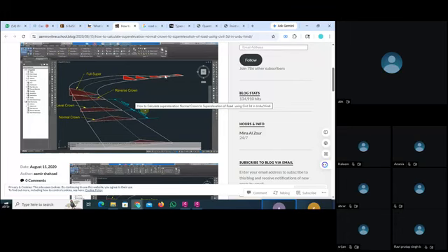When you read the super elevation theory, you can go through all these crown parts. This is the normal crown you can see in this shape. When our shape changes from this to this, it is called our level crown, and in this shape it is shown as our full super elevation. See, we see two things while creating the super elevation: run off and run out.